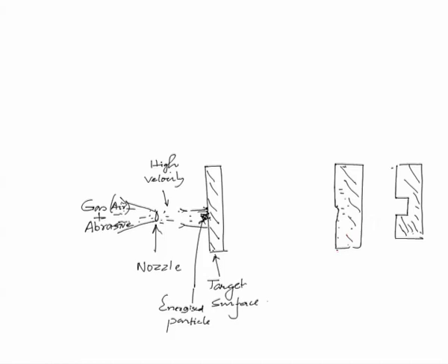But the basic limitation of this process is that the work material should be preferably brittle, like say glass, etc. In these brittle materials, this brittle fracture phenomenon occurs more readily and we get the machining effect more prominently. This process is also known by several other names like abrasive microblasting, pencil blasting, micro abrasive blasting, etc.